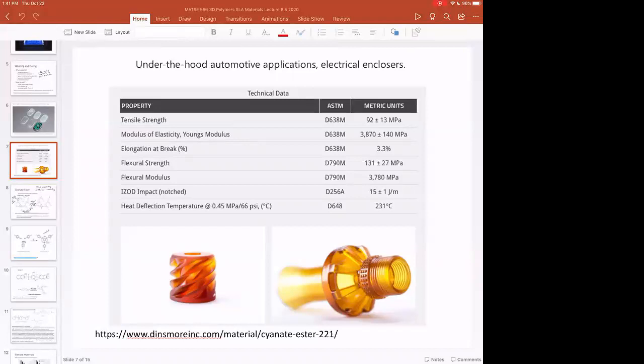Okay, so you should all be familiar with the basic photopolymerization, the UV photopolymerization of acrylates and methacrylates. And if you look at the patent literature, like we're going to do today, a lot of the stereolithography chemistry starts there because that's what works. And that chemistry is fast enough in order to get this liquid to solid transition within 50 to 200 milliseconds.